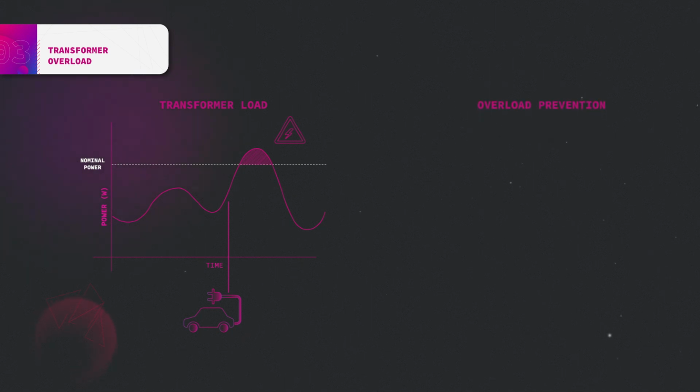If not handled in a smart way, overloading is avoided by upgrading the network with transformers with greater rated powers. Similarly, when the current going through power lines surpasses their rated current, they have to be replaced with ones that have larger cross-sections. To avoid huge investments, overloading can be mitigated by controlling the loads that are causing problems in a smart way.